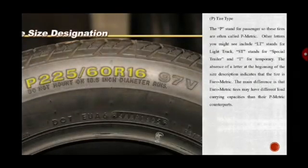Information stamped on the tire sidewall. P is the tire type. The P stands for passenger, so these tires are often called P-metric. Others you might see include LT, which stands for light truck, ST for special trailer, and T for temporary. The absence of a letter at the beginning of the size description indicates that the tire is Euro-metric. The main difference is that Euro-metric tires may have different load carrying capacities than their P-metric counterparts.